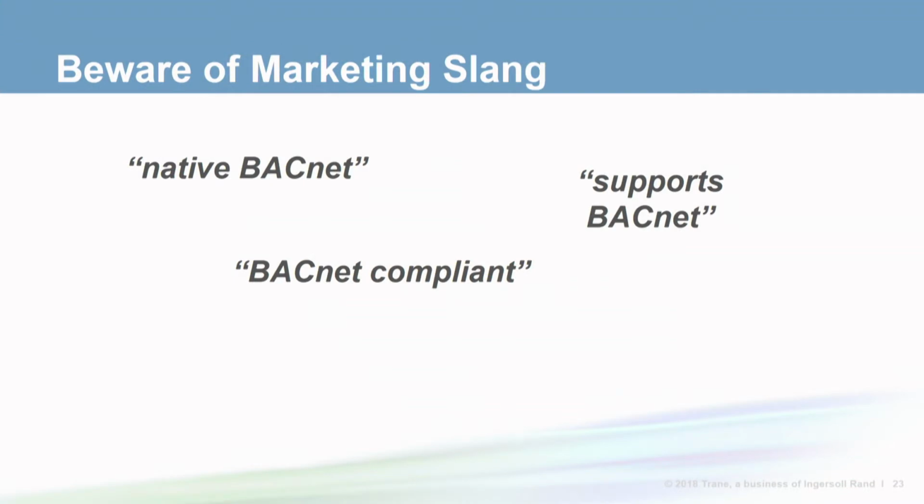At this point, I want to take a sidebar and talk about how BACnet is often marketed in the industry. Beware of marketing slang used by salespeople to get around the question of BTL certification. You may hear phrases like native BACnet, BACnet compliant, supports BACnet, or other variations of this theme. None of these terms mean anything to indicate the quality of their BACnet implementation or the functionality they support. There is no BACnet International or ASHRAE recognized definition of these phrases.